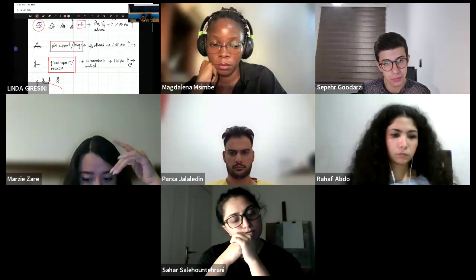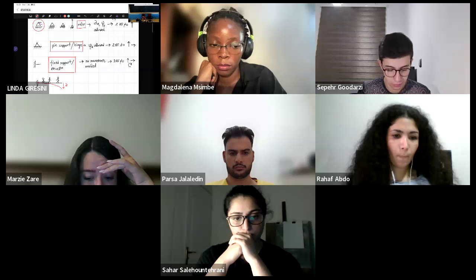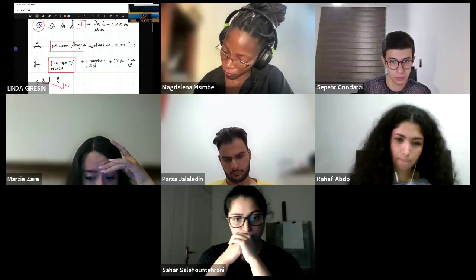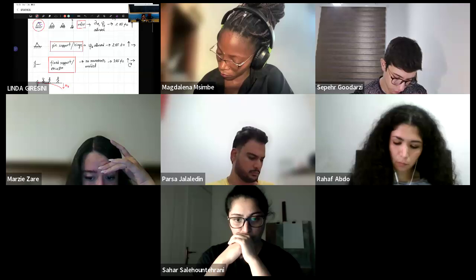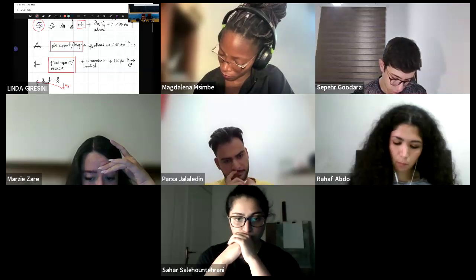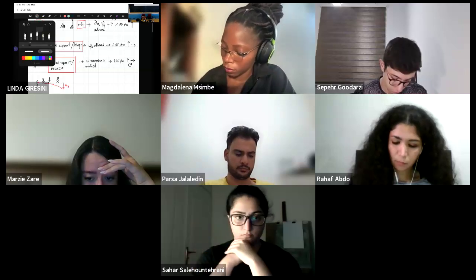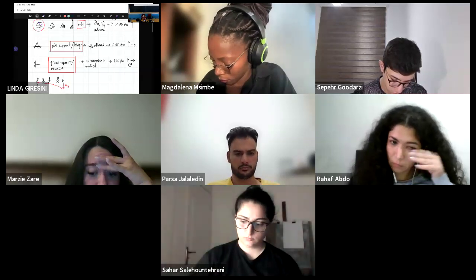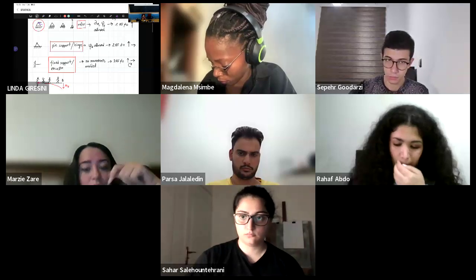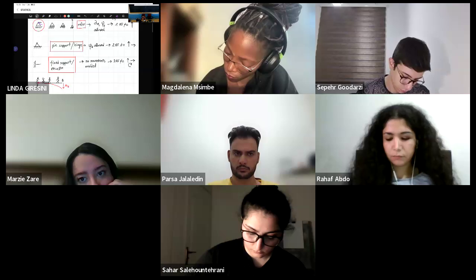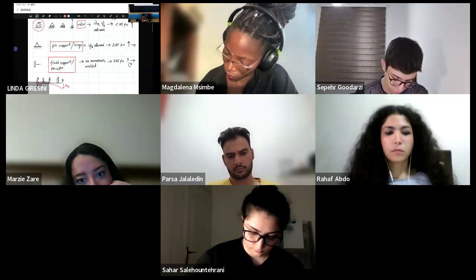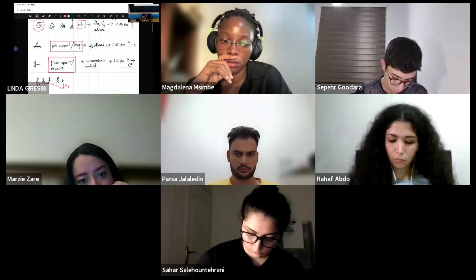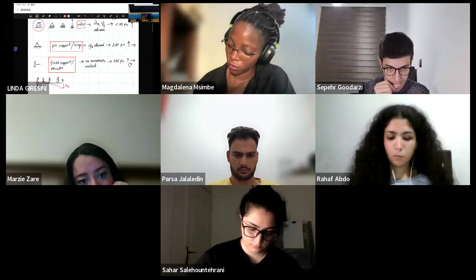So you'll have a deflection at the free end, let's call it uy, doesn't matter the symbol. But at the fixed support, the A point, doesn't move. Also, it doesn't rotate. So in the deformed shape, if at the beginning the angle was 90 degrees, after the deformation, it remains 90 degrees.